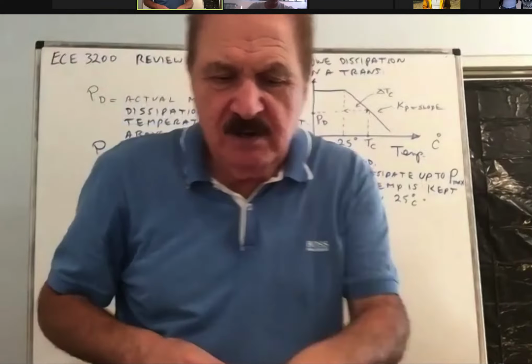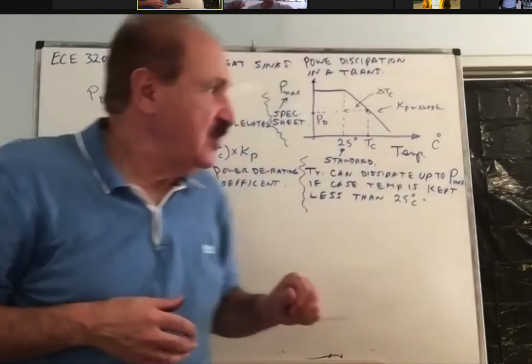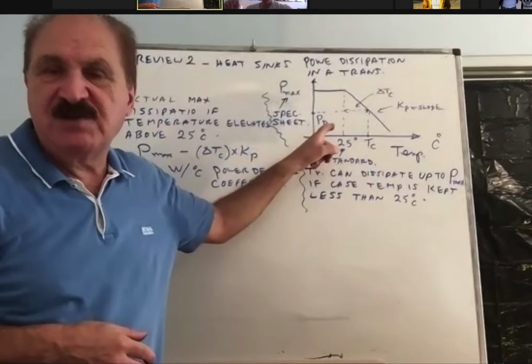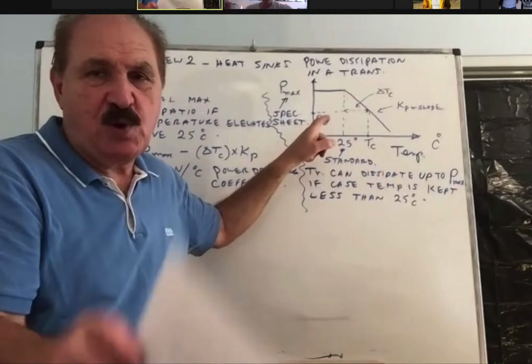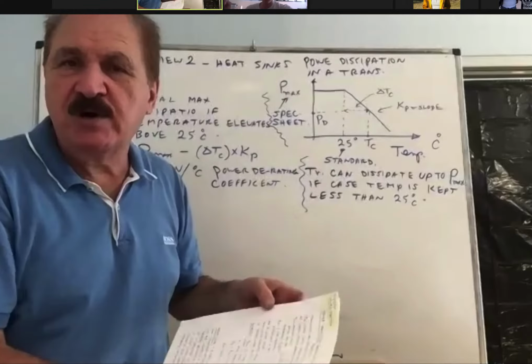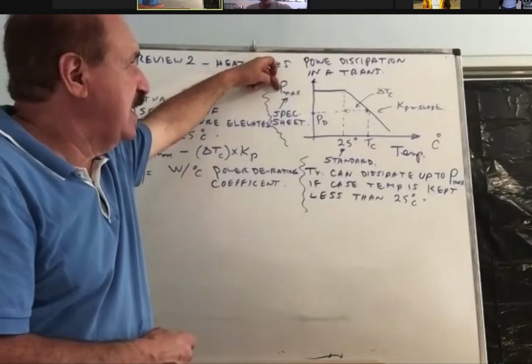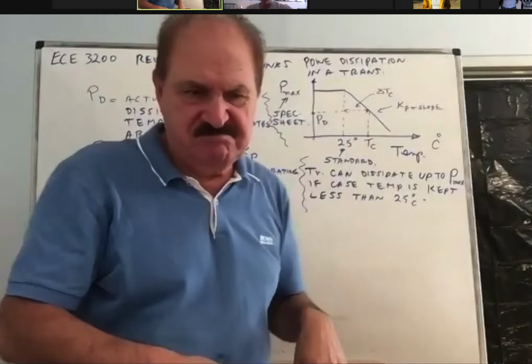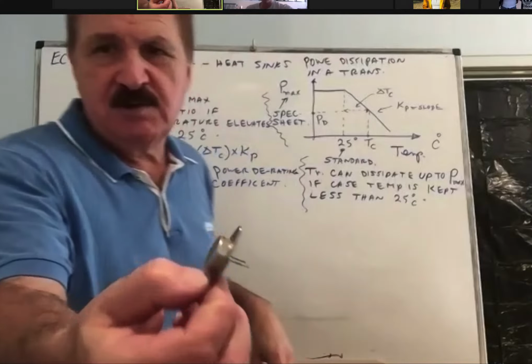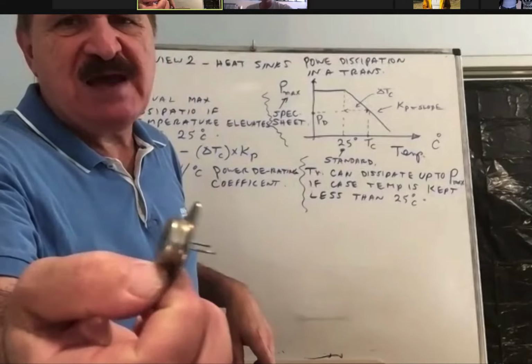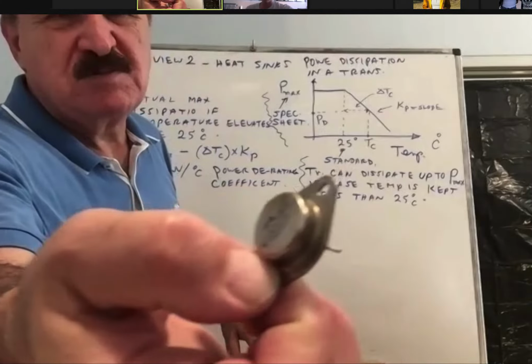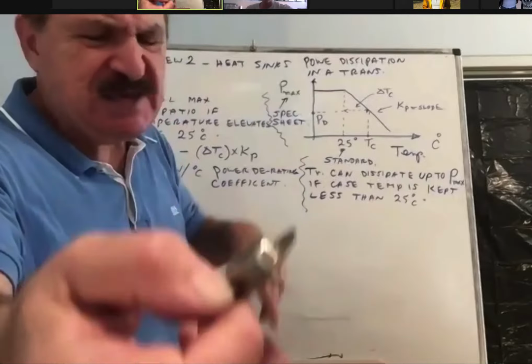Topic number 1 in the power transistor is this curve, which you have in page 1. It's called the power derating curve. The manufacturer will specify what is the transistor rating. For example, this transistor, its Pmax is about, I think, 150, but let's take it for 100.